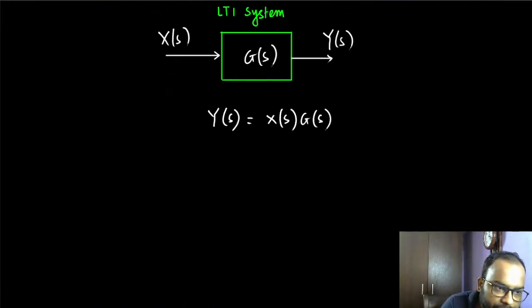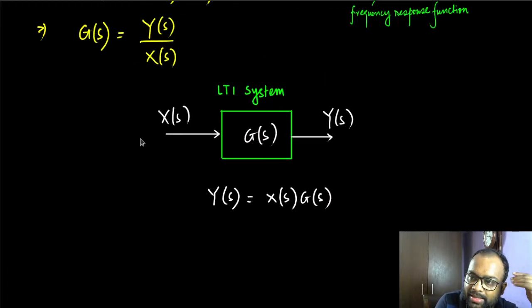No issues. Now try to understand that we are talking about dynamic systems. This is something we discussed in our signals and systems classes. When we say dynamic systems, we are talking about systems for which, in order to calculate the output at a present instant, we need the knowledge not only of the present input, but also the past inputs. So the present output depends on the present as well as possibly the past inputs. There is another type of dynamic system for which you need the knowledge of future inputs, but that's not possible in an analog case.